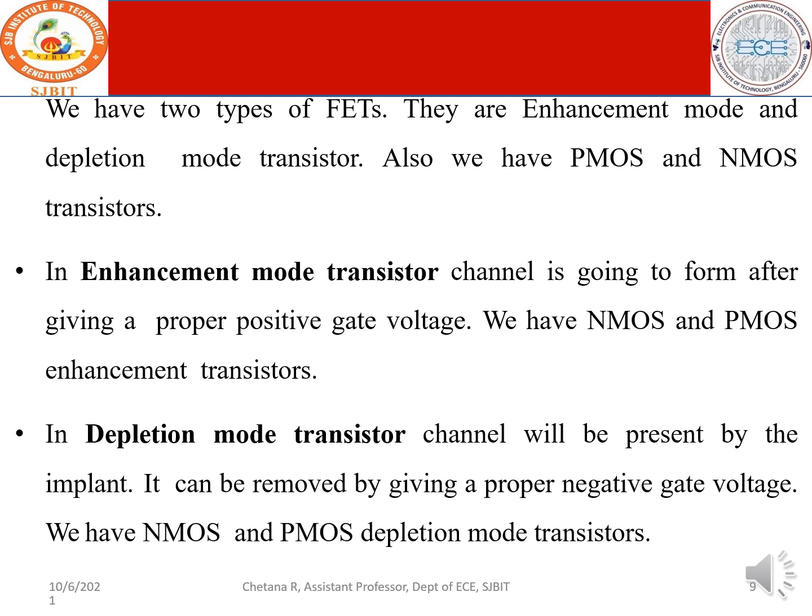But during fabrication, there is no channel in enhancement mode. In depletion mode, the channel will be present by the implant, that is during fabrication itself. However, if you want to remove the channel, you have to give appropriate negative gate voltage.